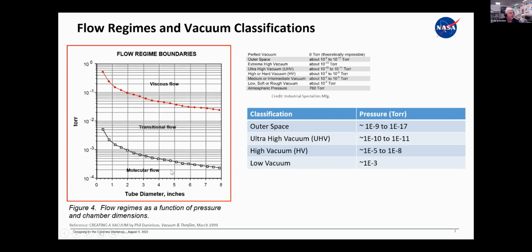Molecular flow is what we're going to emphasize and talk about more here, and it's really important. And again, it's something kind of not intuitive. Viscous flow is, as you might expect, where you are creating a differential pressure and a high density collection of particles are moving into your pump, because you've created a lower pressure than, say, what's in the chamber at atmosphere.